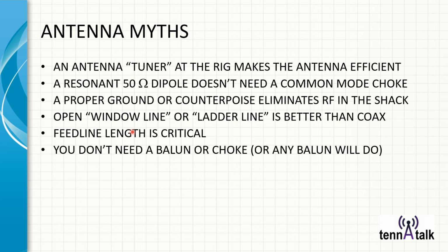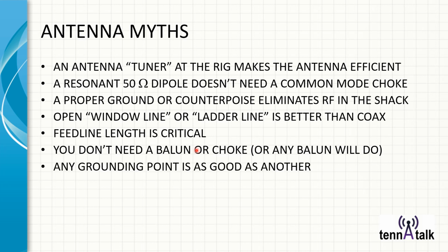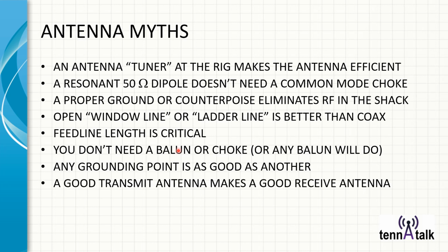You don't need a balun or a choke, any balun will do. No, again, we'll find out. We'll actually go through the actual design and calculations of exactly what kind of balun and or choke you might need. Why? Any ground point as good as another? No. You should always have your rig grounded, well grounded in the shack, and of course you should use a good lightning arrestor outside, upstream of the rig, that is grounded to an excellent ground rod deep in the ground. But some antennas don't need grounding. Ideal dipoles don't need grounding.